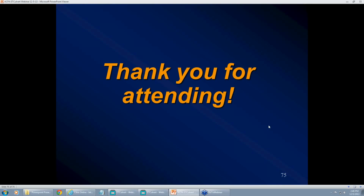Another was a quick way to see if your design has worked or not for a culvert. Seems like you'll have to sit through many output pages. It's usually like 25 pages. And so a quick way to check if it has worked is to verify that all the ratings are above 1.0 and that you meet the serviceability requirements. And this is all on one page. It is? Yep, that's right. However, that page is generated for each of the fill depths, so that single page must be checked for each of the fill depths. Okay.